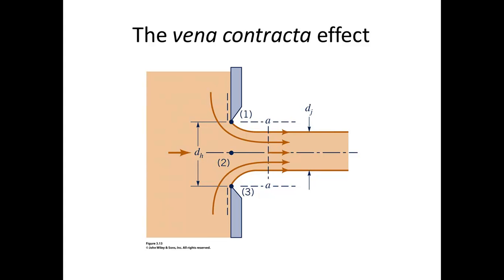And as it gets to 3, well, it's not going to make a right angle turn. That would require bringing it through an abrupt right angle, which means a radius of curvature of 0, which means infinite acceleration, right? Because accelerating a fluid can be either changing its velocity or its direction. Here we're doing a 90-degree direction change, and that's going to be gradual.